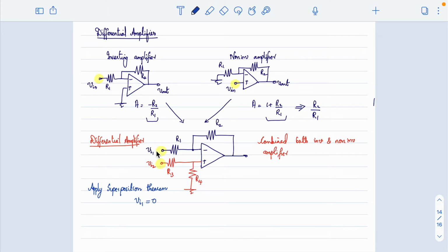Now generally when we look for an amplifier, especially a differential amplifier, the amplifier should respond to the difference. The amplifier should amplify the difference of the input signals. But now one input I am giving to the inverting terminal, another input I am giving to the non-inverting terminal. Now if it does not have equal gain, both the signals are amplified by different factors, which is not what we generally want, right? Because we need to amplify the difference with one amplification factor, and that cannot be different.